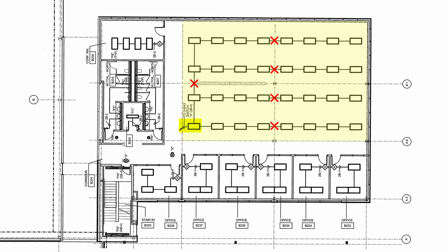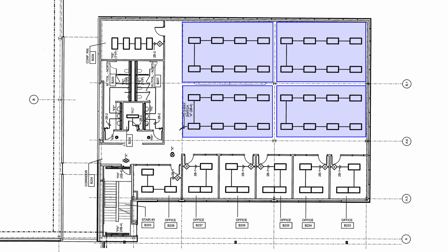Next, the new lighting zone circuits will be established by connecting necessary fixtures and running unswitched power to the start of each zone, as shown here. The advanced load controller that is controlling each of these zones is to be wired in at the start of each of these newly defined zones. Unswitched power should be entering the advanced load controller, and only the fixtures being controlled by the advanced load controller should be on the switched power coming from the advanced load controller.